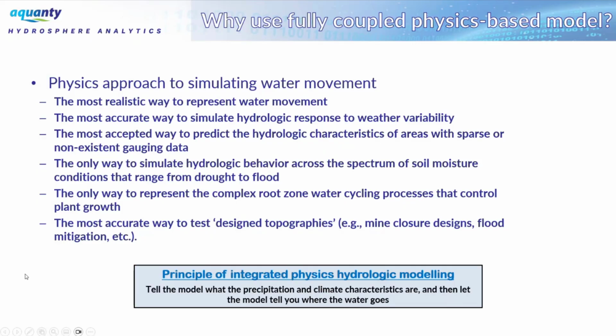This physics-based approach is really a strong overall approach to simulating hydrology in quote-unquote unknowns. So this could be under unknown climate conditions. If you're estimating a recharge rate as a boundary condition for a groundwater model, for example, the way that you calculate that recharge rate is going to be predicated on historical observations.